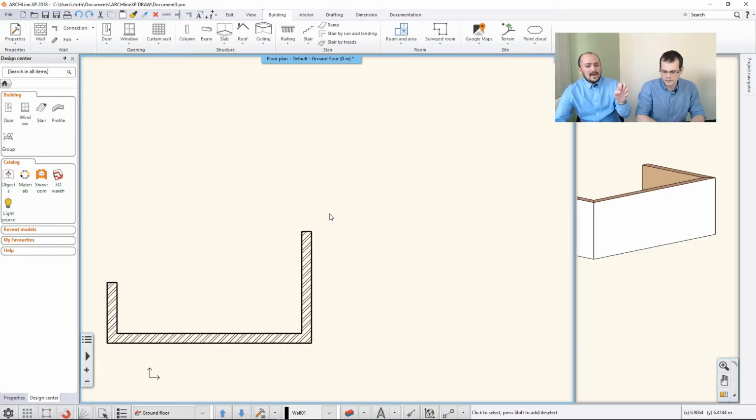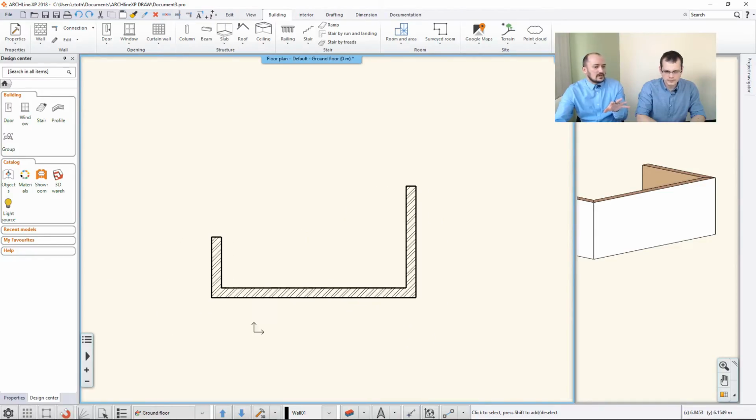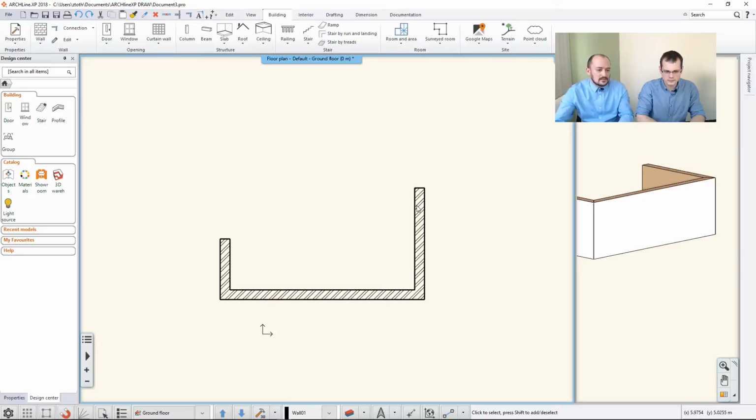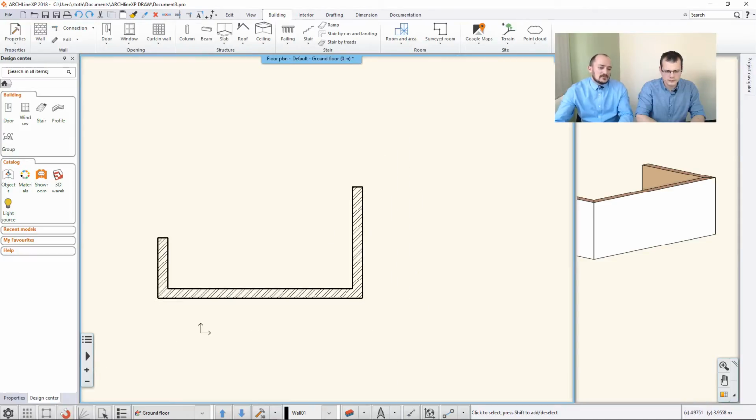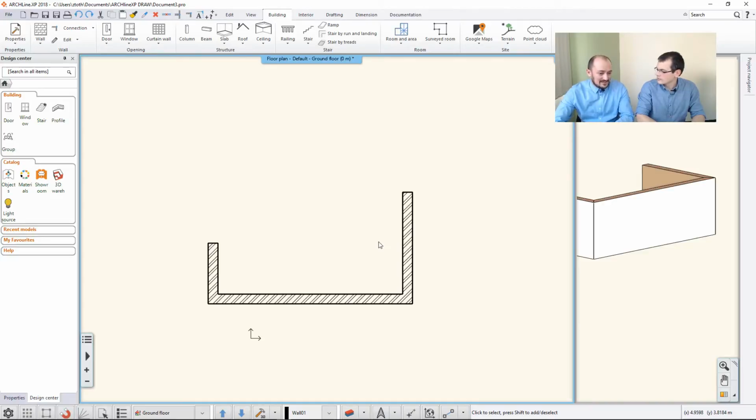And if you would like to pan the drawing, to move it around, then you just keep holding the wheel. I mean, you just click with the wheel and keep holding it like a regular mouse button and move the mouse. That's how you move this content around. And when you release, then it's there. So zoom in, zoom out, and click and drag the mouse wheel. This is how you pan the content.